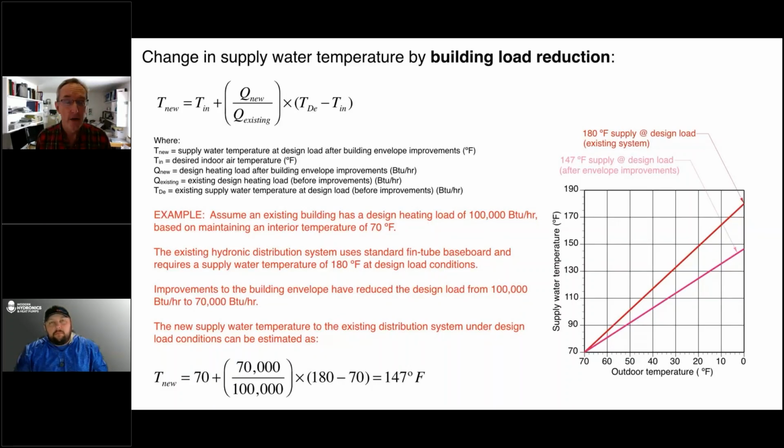I don't know how you would evaluate something like that. There are some panel radiators, which we don't see much in North America, but in Europe, one of the trends is several panel radiators that have what I'll call micro fans built into them, specifically for that purpose. As the water temperatures go down, the natural convective heat output also goes down.